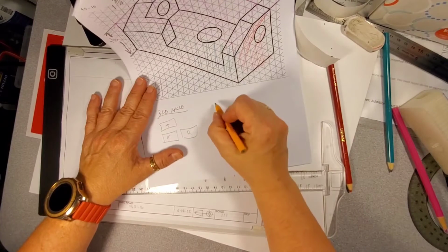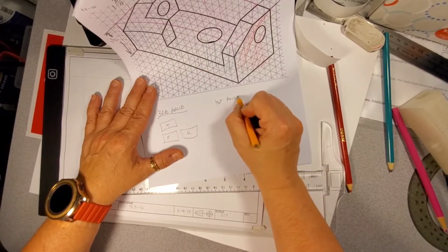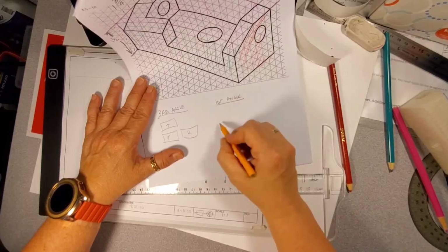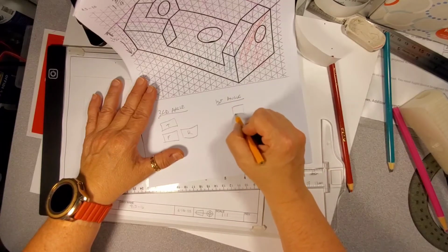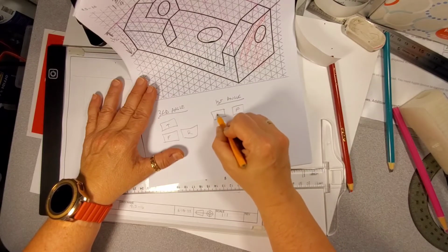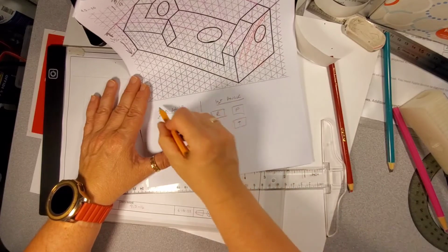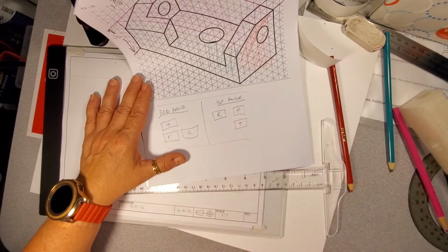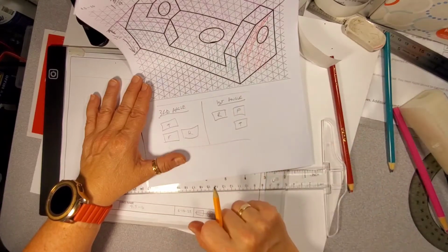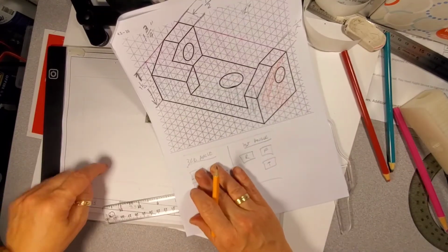When you do first angle, when that time comes, because you're going to do the first angle on your own for this guy, it's what? Front, right, top. Always do this for yourself until you can do this automatically for yourself. Get it?